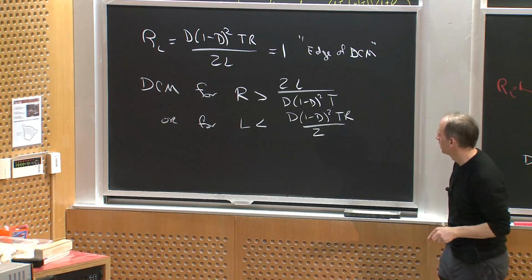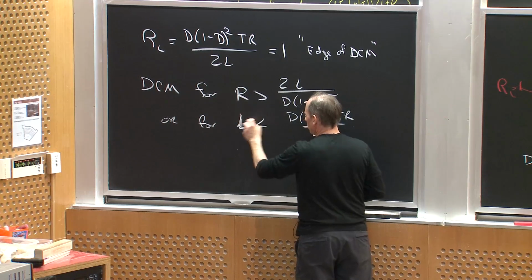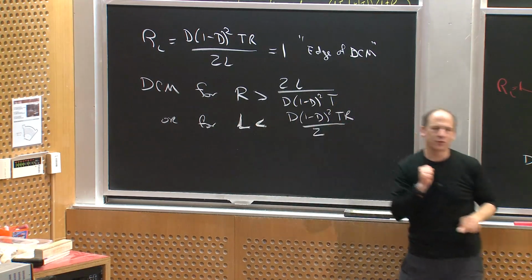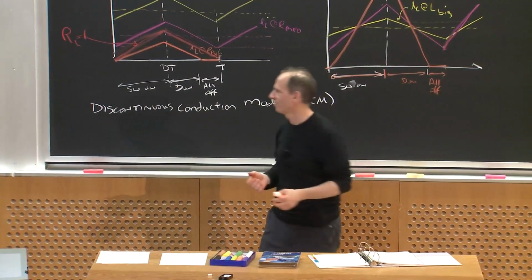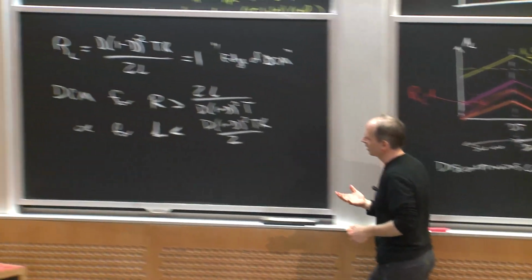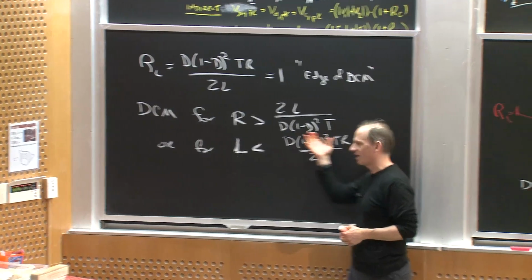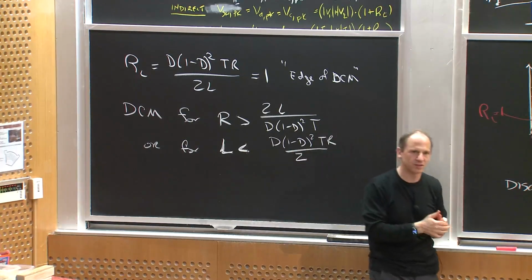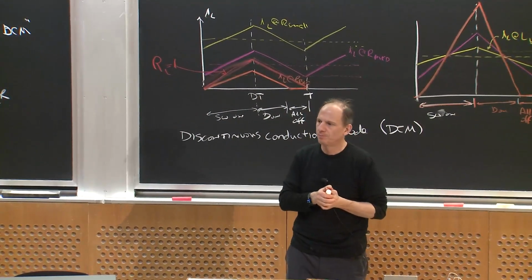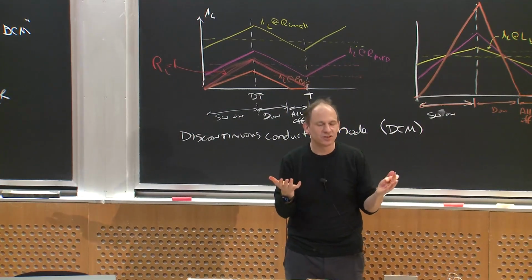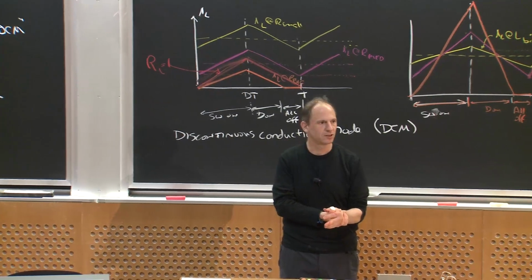This value of L is sometimes called the critical inductance in the literature. There's nothing very critical about it, but all it's saying is if I go out and pick a big inductor bigger than this for the specified operating conditions, I'm not going to run into discontinuous conduction. But understand, in a lot of cases, for some operating mode, you're going to have to run into discontinuous conduction.